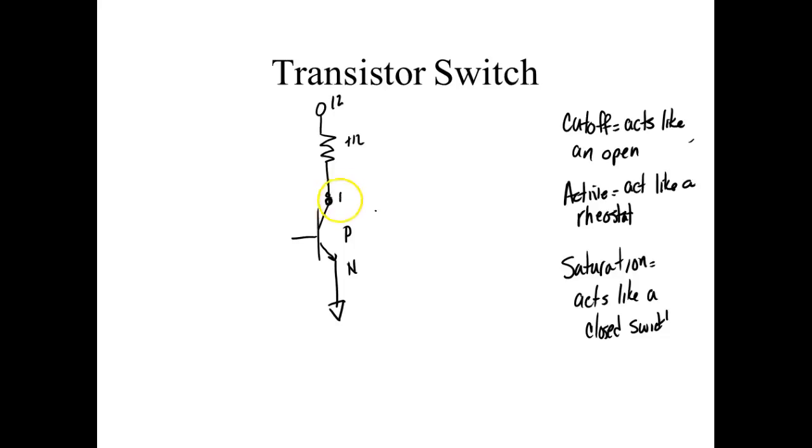And then this gets kind of confusing. This is an N up there. Well, what we do is we have to forward bias this junction. Forward bias means we put a positive on the P and a less positive on the N, right? And we have to reverse bias this junction, for reasons we're not going to talk about. So even though this is N, we point it toward P, the positive. And this is the way you forward bias an NPN transistor.